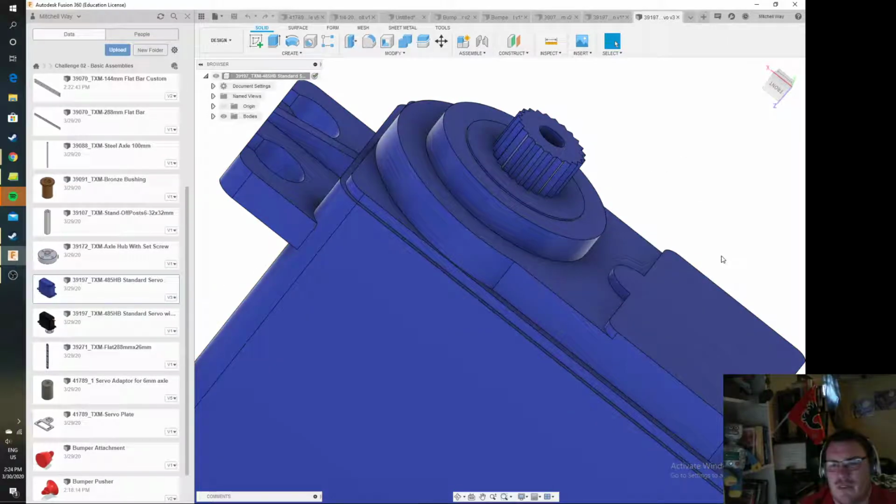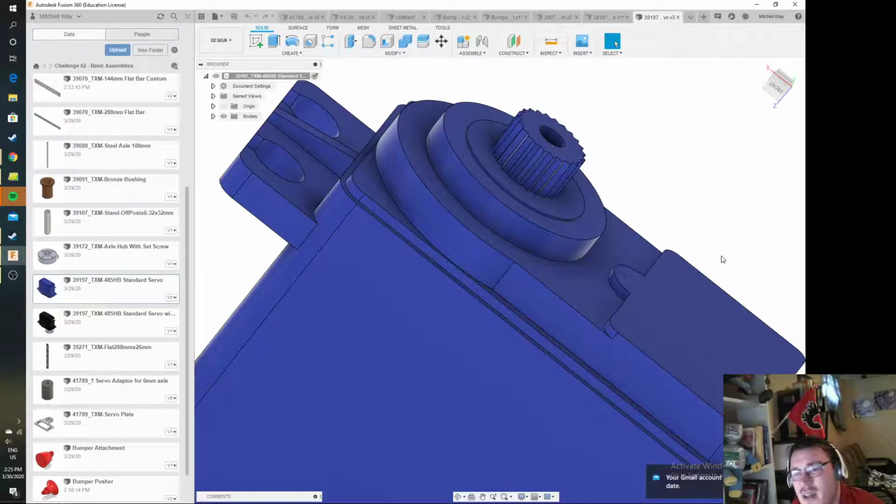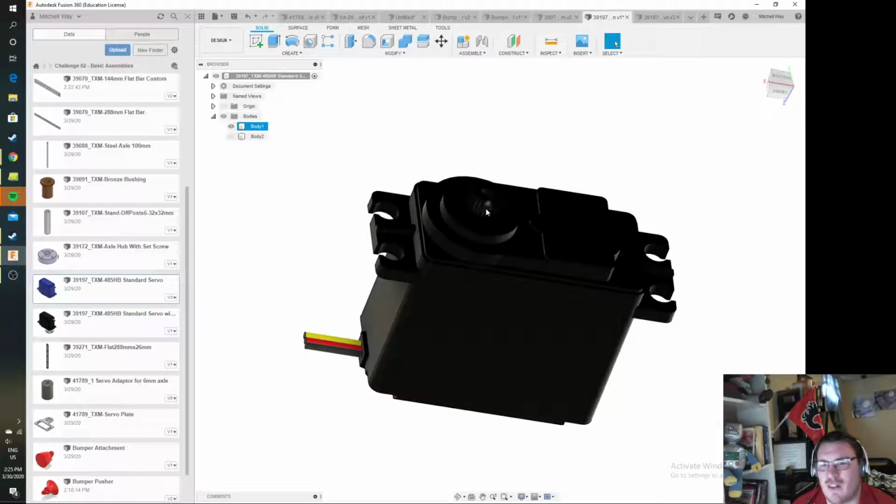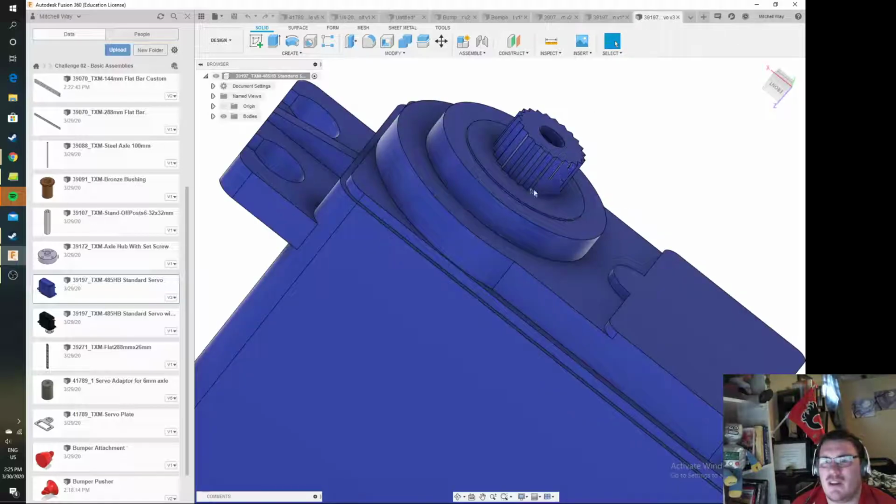This is the end of a servo. And the end of the servo, if you're lucky, is made out of a bunch of brass gears that are actually going to help you attach things. They are not very strong. Servos by nature are not the strongest component on your robot, and I wouldn't treat them that way. If you put your subsystems directly on the horn at the end of your servo, you're prone to breaking it.